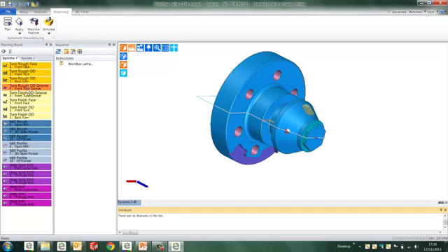Now there is certain elements of flexibility. I may wish to mill the part before I finish turn the part, and we can start to drag and drop, and we can reorder the process as we see fit. There are also elements of safety built into this to stop us making bad decisions.